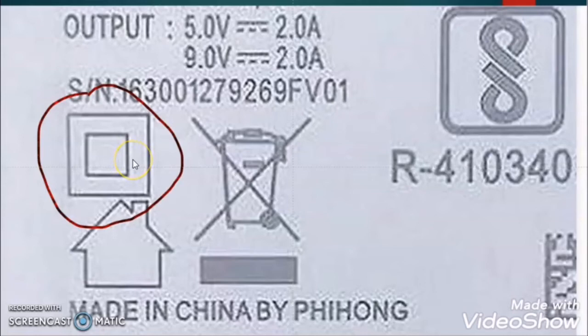So even if the phase wire or neutral wire detaches, it will touch the inner part of the insulation, and you are always in contact with the upper part of the insulation. So first of all, there will be no chance of an earth leakage fault, and even if there is an earth leakage fault, it will not be in the part which you are touching. It will be with the inner part of the insulation.